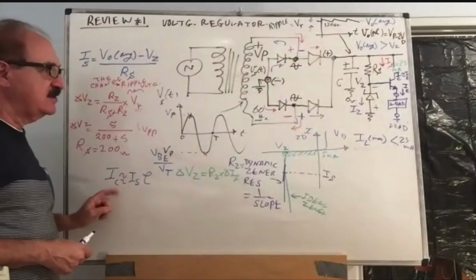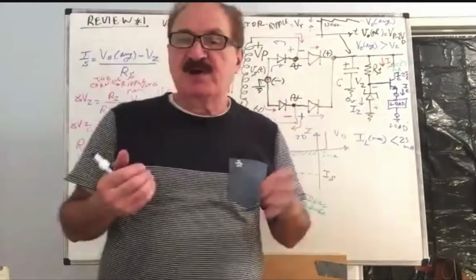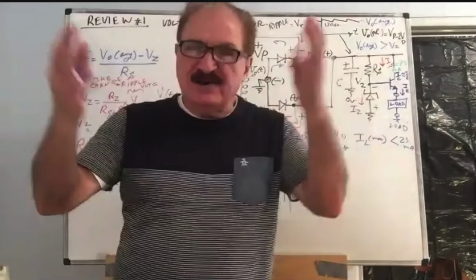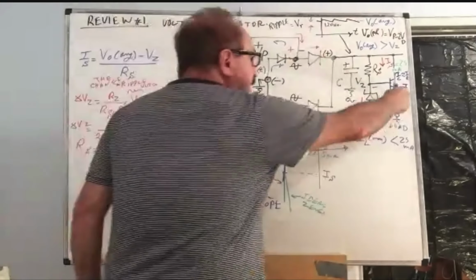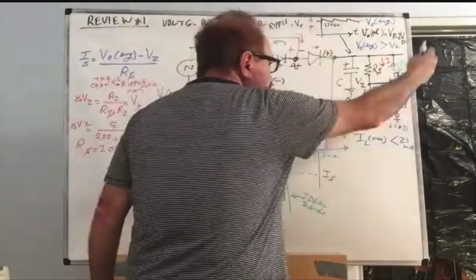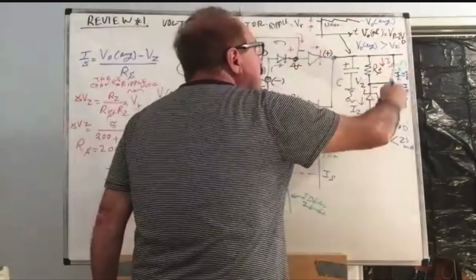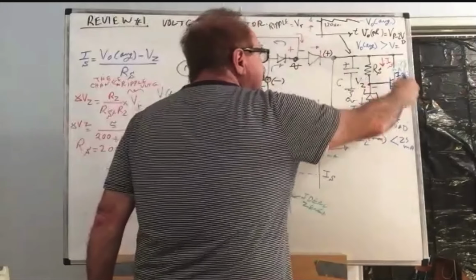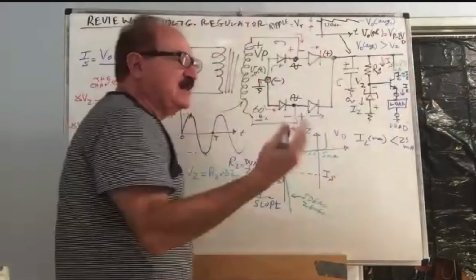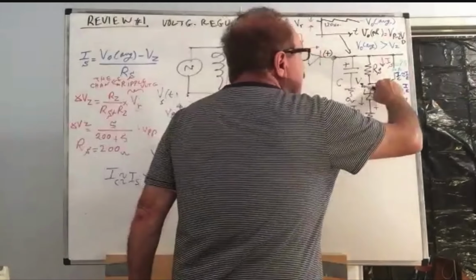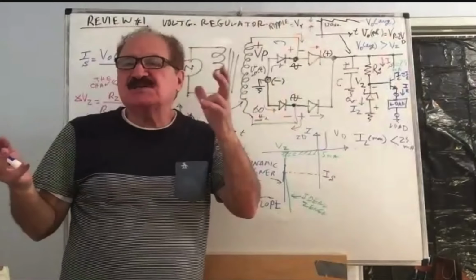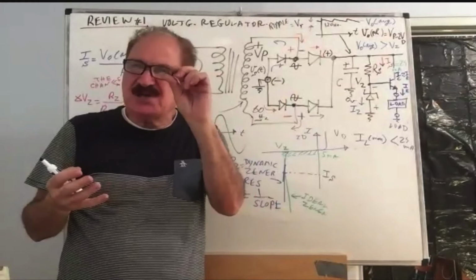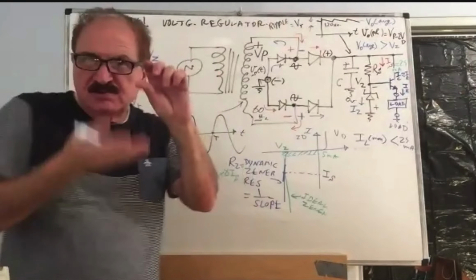The current in the collector can change by a factor of 9 times, nearly 10 times. So if the load current changes by a factor of 10 to 1, I'm expecting that the collector current will change by that amount, and the VBE will change very little, 50 or 60 millivolts maybe, which can be neglected due to the loading effect.